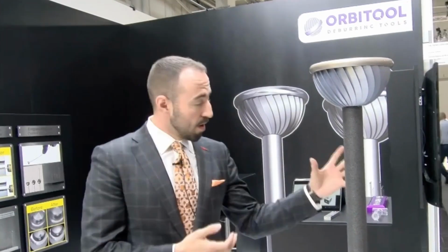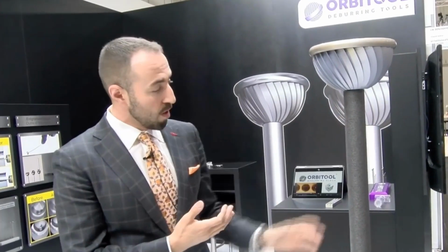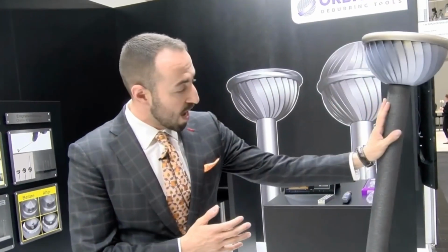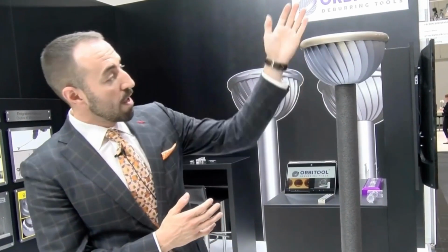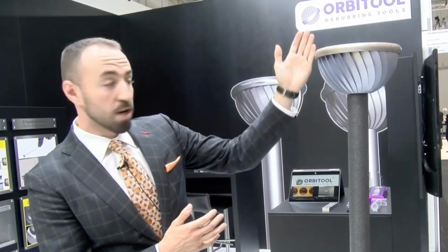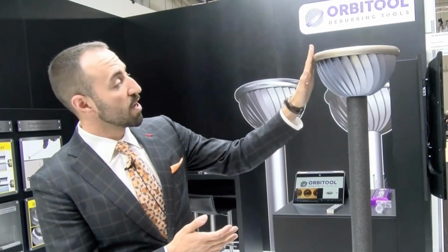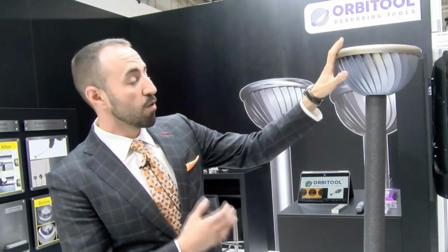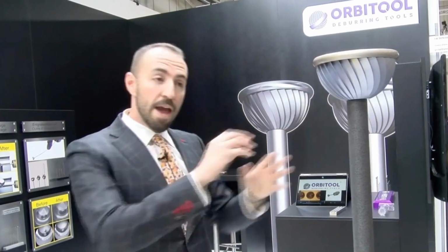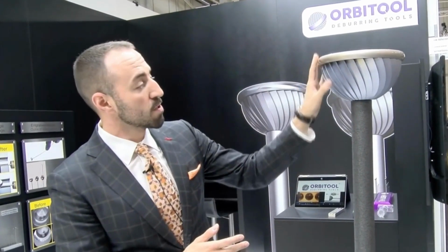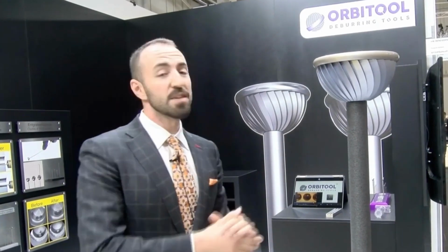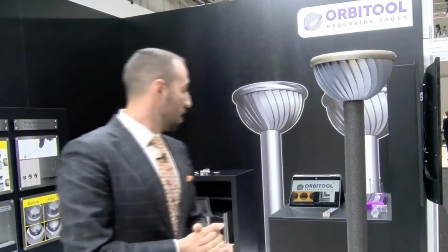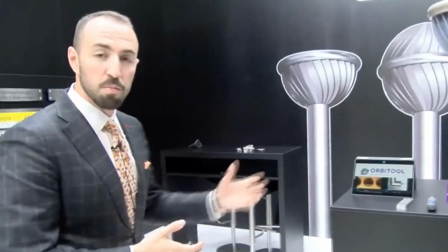So the main principle of this tool is two main components. It's a flexible stainless shaft, the carbide cutter, and the protective ring above the carbide cutter. The purpose of this ring is to protect the wall surface of a cross hole. Any sort of wall surfaces where you don't want any damage, this ring will be protecting those. And the carbide cutter is only going to remove material selectively at the intersection edge. So we can step over here and watch a couple of videos on how it's working.